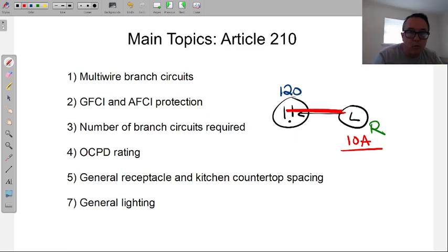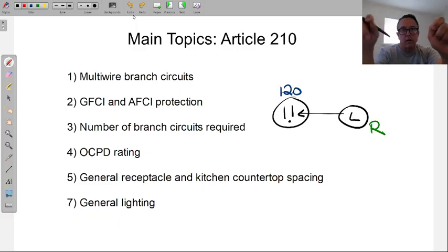It happens only if that load is on. If you turn this off and no longer have the connection, no longer do I have amperage, I still have resistance and voltage, unplug and plug in, no arcing. Because homes, right? People, carelessness, you can't tell somebody, hey, don't forget to turn that lamp off before you unplug it. Everybody just yanks the cord. Arcing happens every single time a load is on and gets unplugged.